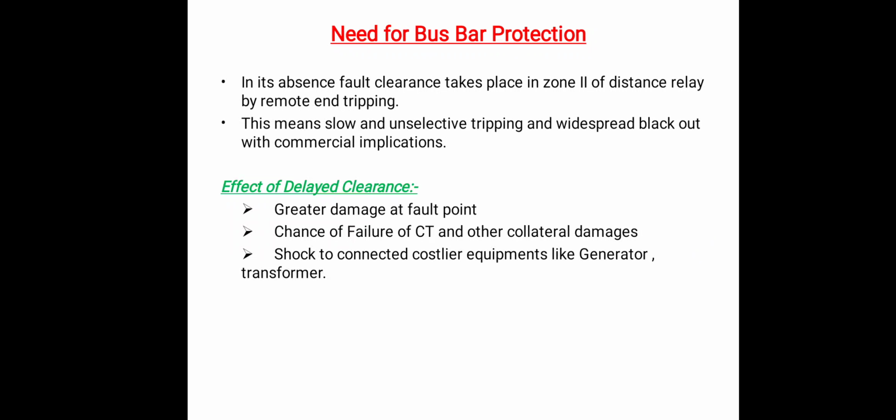What is the need for busbar protection? I earlier said busbar faults are rare, but if a fault occurs in our power system, considerable damage and disruption of supply will occur. In the absence of busbar protection, fault clearance takes more time because the fault clearance will take place in zone two of the distance relay by remote end tripping.